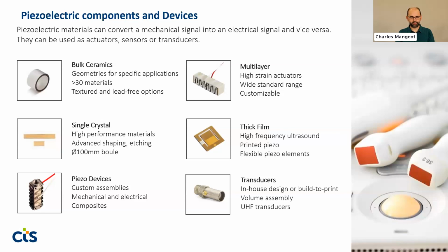Talking about piezo, some of our products, we do bulk ceramics, which is based on pressed powder. We do multi-layer through tape casting and interleaving with internal electrodes. And we do single crystal products for high performance applications. We also do thick film, so piezoelectric devices that can be printed, typically for higher frequency applications or for flexible applications. And then we have a range of devices and transducers that are designed using these products and adding some more features, assemblies, mechanical parts, wiring, and testing.